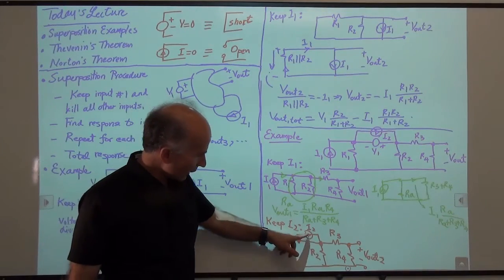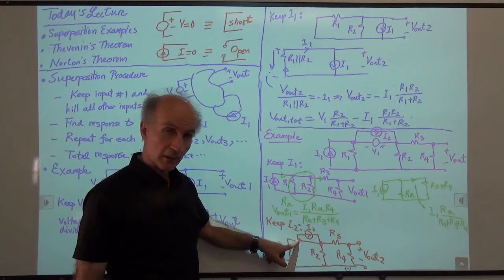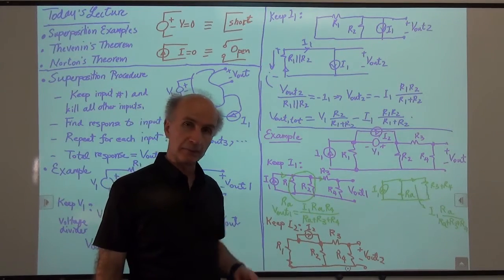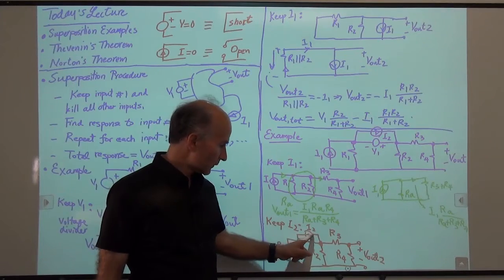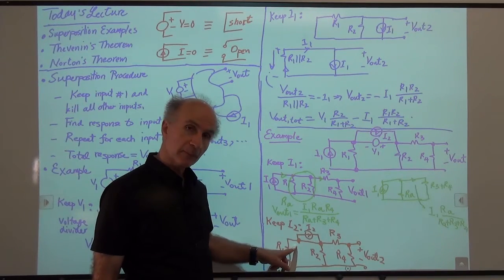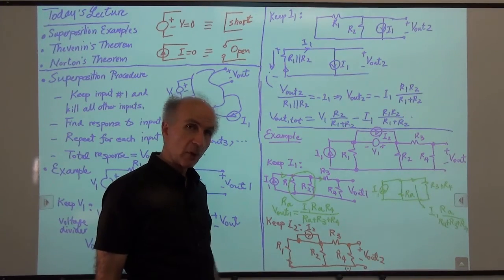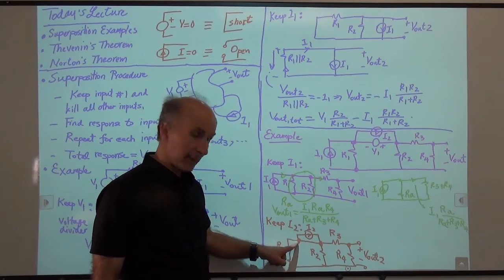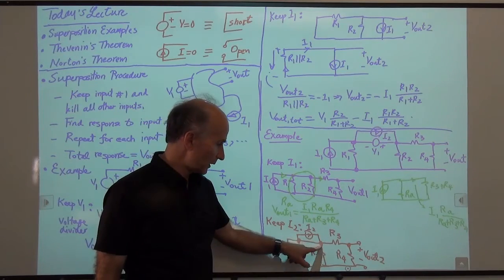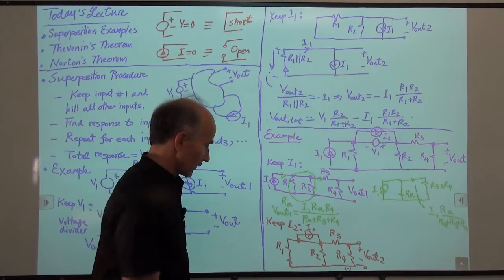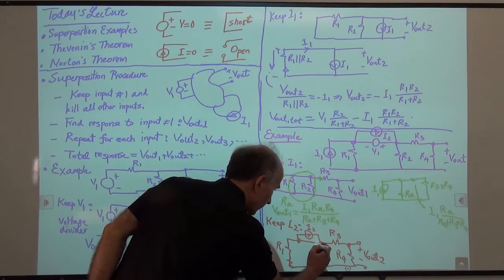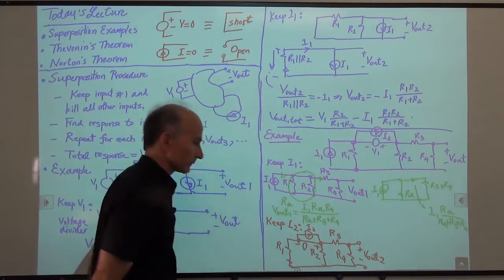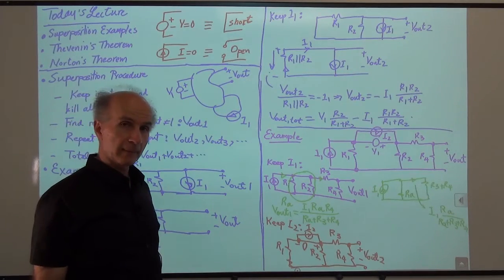All right, so if I have I2 and I have a piece of wire, and then I have some other stuff, which way would I2 want to flow? I2 prefers to flow through this wire here, right? It doesn't have anywhere else to go. Or, if we don't like that, we can think of it this way. This piece of wire guarantees that the voltage difference between here and here is 0, right? Okay, so this voltage difference from here to here is 0 volts. Is that okay? All right.